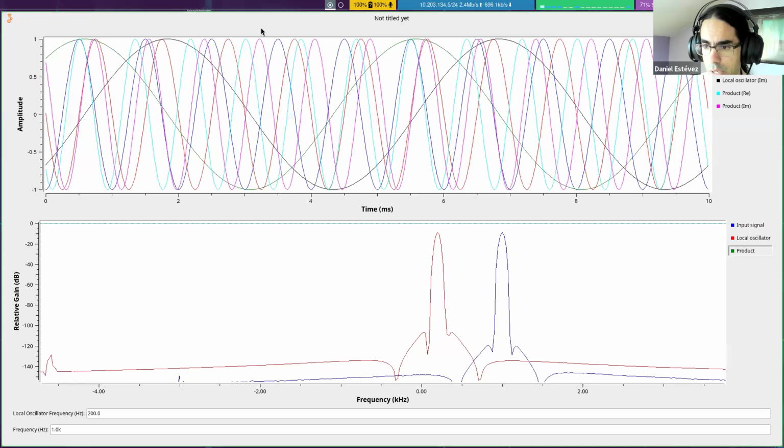And because the frequencies are in the exponent, what happens when you multiply is the exponents are added together, so we get the sum of frequencies. So hopefully the thing we are getting in here should be sinusoids at 1200 hertz. And if I show this in the frequency domain, that's exactly what we get, a 1200 hertz tone.